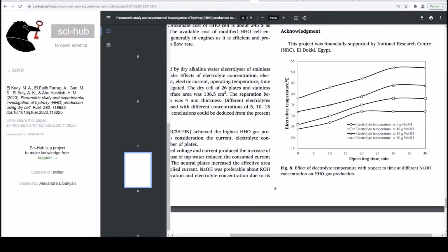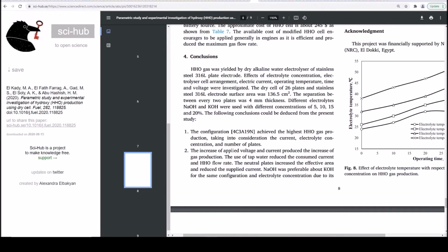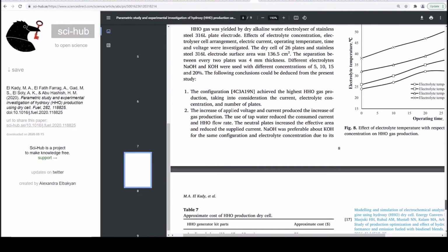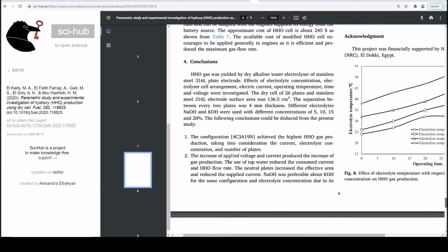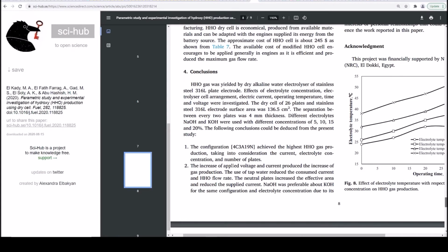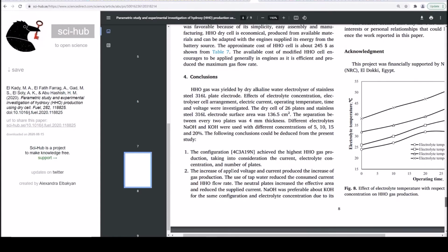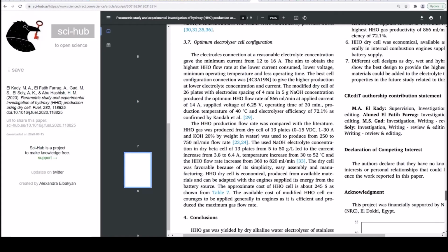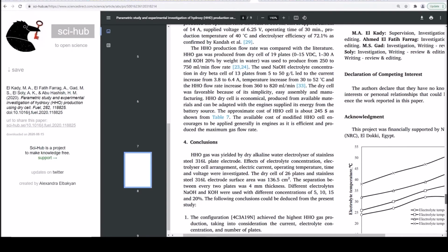So it's very possible to design a cell for lower power density, higher efficiency, longer life, and achieve those three targets. You want to use less electrolyte, you have less corrosion, and you also want to use a lower temperature as well as a lower cell loading. Obviously, if you run more current through that electrode, you're going to create more heat, and so the heat is really related directly to the power density.